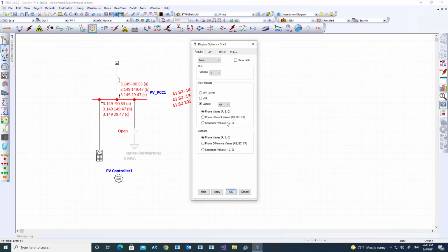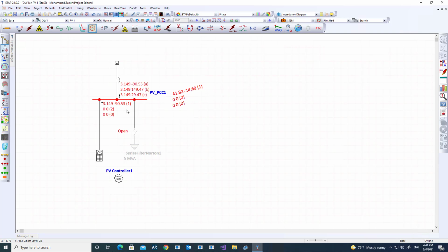And if I just make sure that I'm just using the positive sequence component here, you see that you have a great deal of reactive power control because voltage dropped to 40%. You're injecting quite a reactive current. This is -40, -90. Okay, so you see that there's a great deal of reactive power current as compared to the load flow condition that mostly we are injecting active power. Okay. So you can use this to determine the angle of the current. Okay, so right now you see that it's around minus 50, 70 something. If you put the faults at different location, you see that this angle can change.